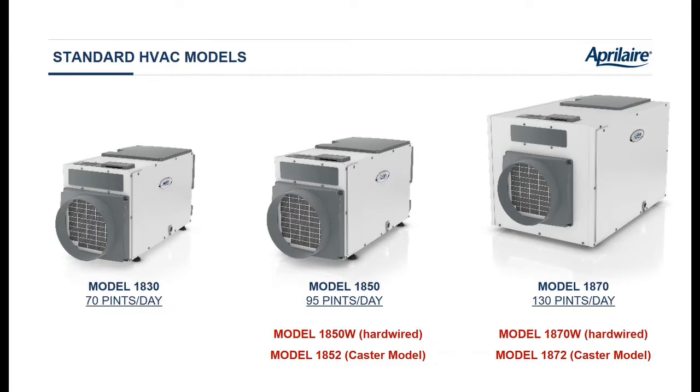When you get to the 1850, there's a couple options. 1850W is a hardwired unit. Some municipalities require that the dehumidifier be hardwired if it's located in an unconditioned part of the house. That's code. Usually the logic behind that is you don't want rodents gnawing on the power cords. 1852 has casters instead of the adjustable feet.